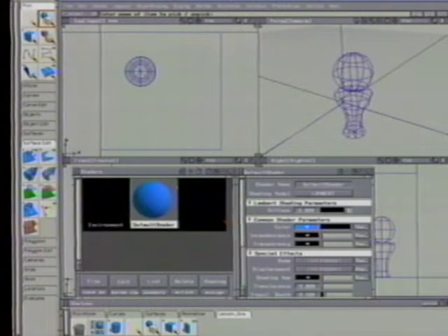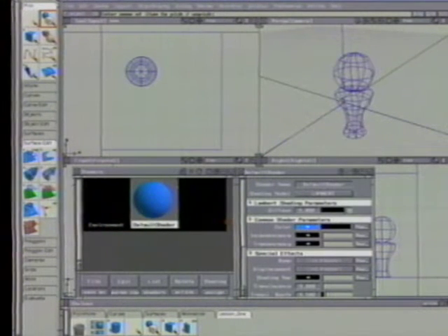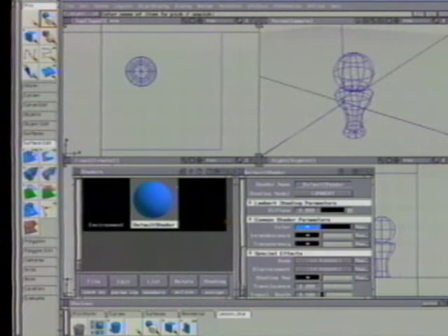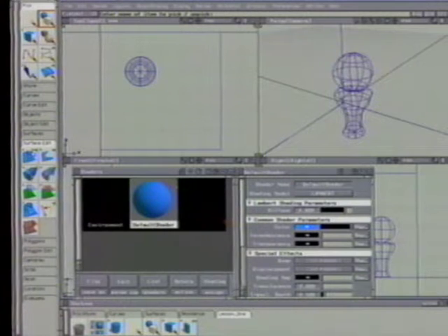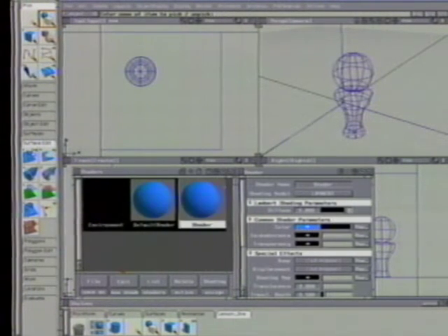You'll now create and apply shaders into this simple scene. In this scene, there are two walls, a floor surface, a column, and a sphere. You will begin by creating color shaders for the wall, then create a transparent texture for the sphere. You will then create a pattern for the floor and a marble shader for the column. You'll begin with a simple color shader that can be applied to the wall. In the shader lister, go to the Edit menu and choose New Shader. Double-click on the shader's name and change it to Walls.